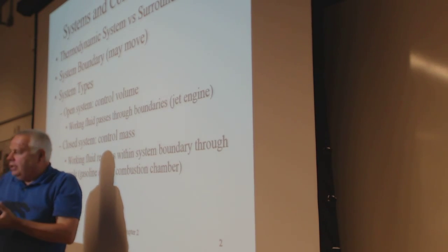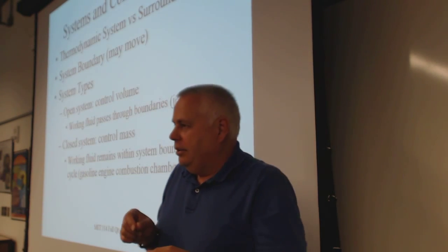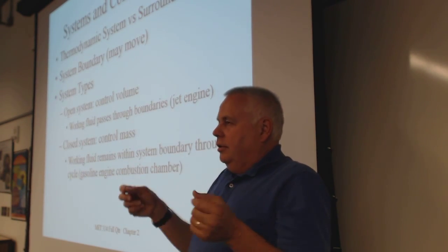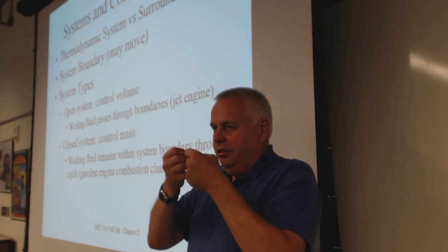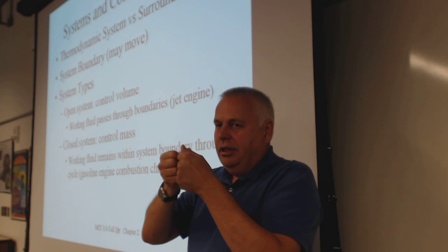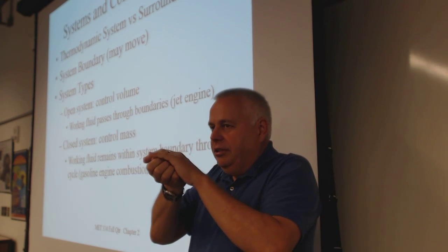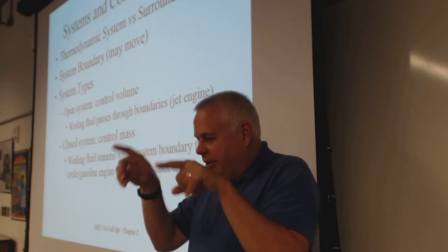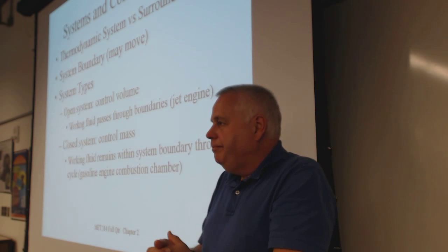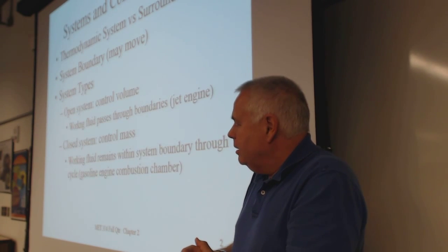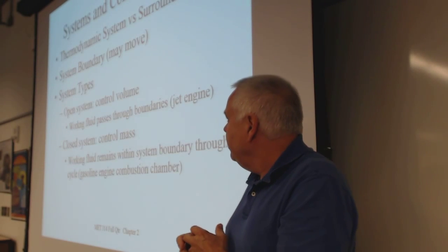Let's say we're looking at a piston engine. Well, we get the intake charge, we light it off, now it's an exhaust gas, it's under high temperature, high pressure, pressure increased when we lit it off, and it's pushing a piston, the piston moves. We're still talking about that gas, so the chamber size changed. But that would be an example of a moving boundary.